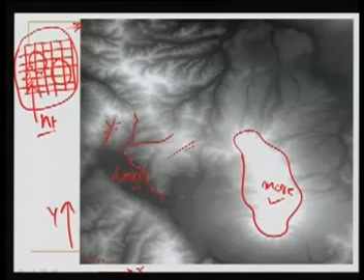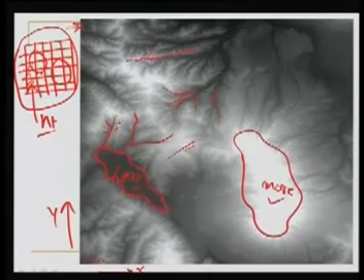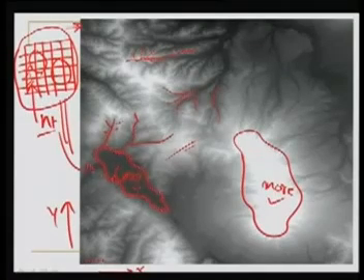Now this is the bottom, maybe a little pond here, and all these are the channels, the water will flow through these. And the white lines, for example, here is the ridge line. So this is a DEM which has now been displayed. So we can interpret several things using this DEM.